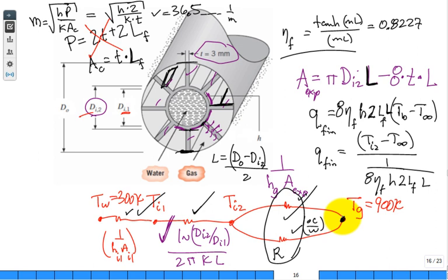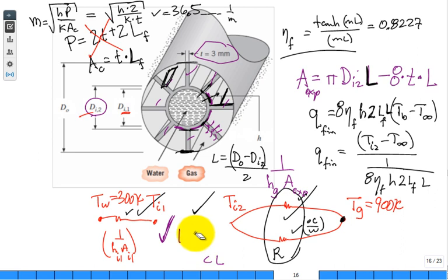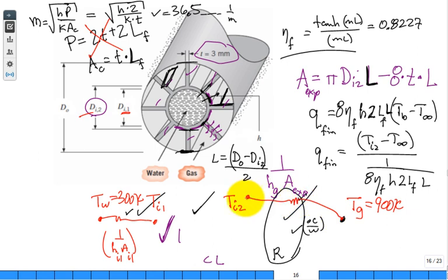Now, if you come back and you want to change the assumption, and you want to have basically that this surface is not the same temperature as that surface, then you have a pathway and another pathway. So what you would do is modify this to have a network that went like this. Go from here to here to here to there.